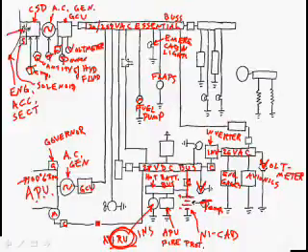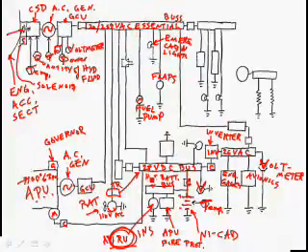Okay. Here is a RAT, a ram air turbine. Now, on some airplanes, for instance, the Boeing 777, the RAT feeds a transformer rectifier, and it feeds the battery bus. Some RATs, 110 volt AC, straight into the essential bus. So it varies by airplane. So let's see if we got the battery, the APU generator, the main generator off the engine, and the RAT. So there's all our power sources.